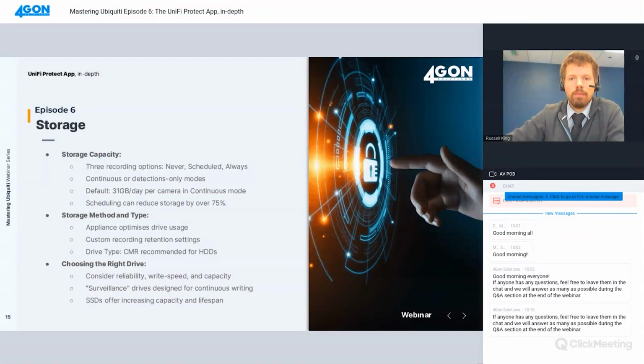So with UniFi Protect, the appliances will use the drive as efficiently as possible for the storage of footage, overwriting the old disk recordings when the disk is full. And using this method is problematic using a standard hard disk or SSD, especially if the footage is being recorded at a high bit rate, as the drive will be working constantly and will eventually exceed the read-write design limitations of the drive. So let's consider both of these factors separately. The storage method,